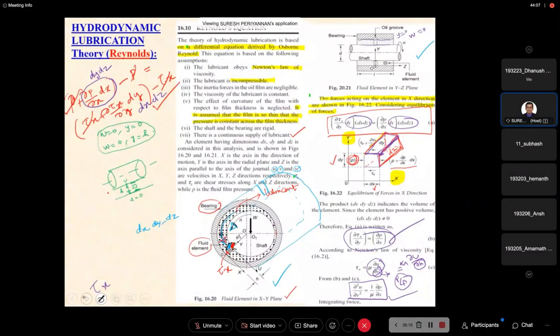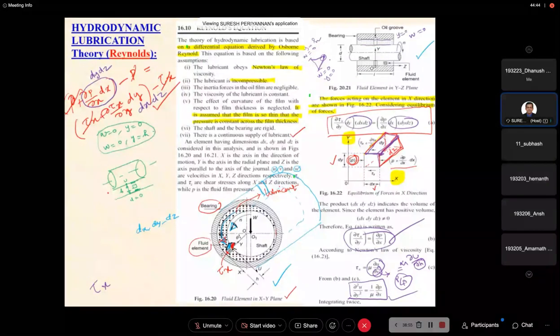But even so, as you might have studied, in the middle of the fluid layer the velocity is higher, and at the boundary it is going to be 0. So w is equal to 0 when y is equal to 0 and when y is equal to h, with respect to the z direction. Now how is this velocity changing? We would like to understand this behavior, hence we want to derive this velocity with respect to the z direction.